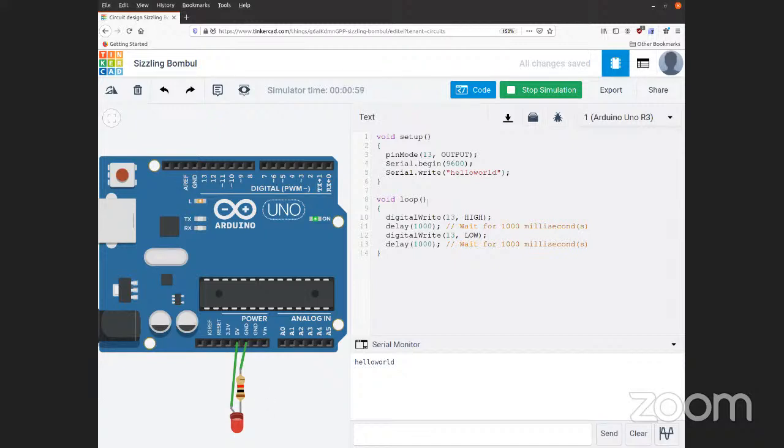The second thing that I would have you do is write a blink program. But luckily for you, the blink program is already there. And let's dissect it because it will teach us about using the Arduino pins. So in your setup function, there is a statement that says pinMode. Now every pin can either be an input or an output, which means the pin can either receive a signal or send a signal. What this statement is doing exactly is it's setting pin 13 to be output.